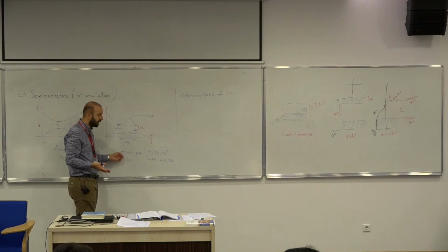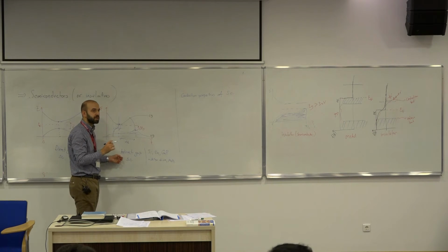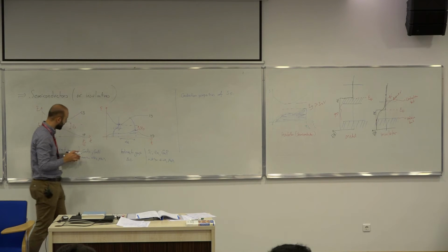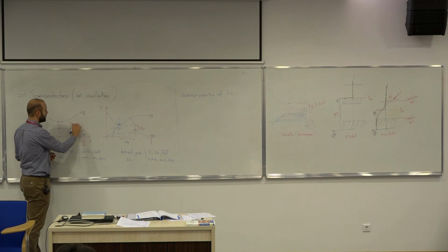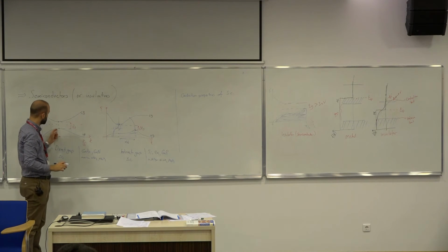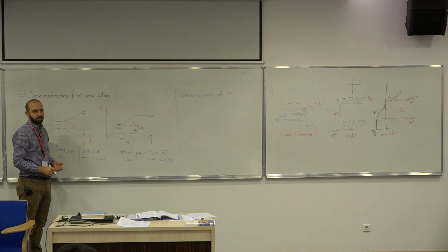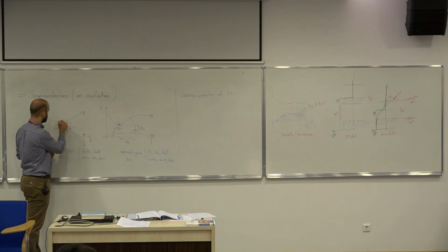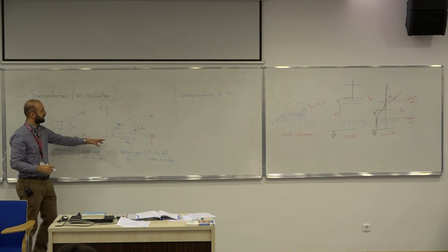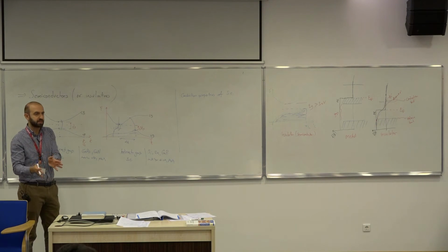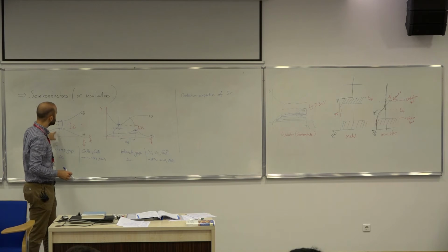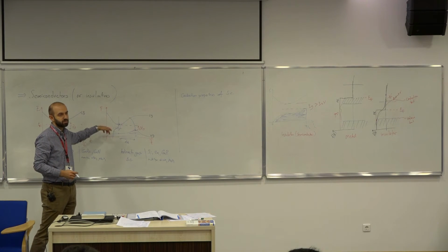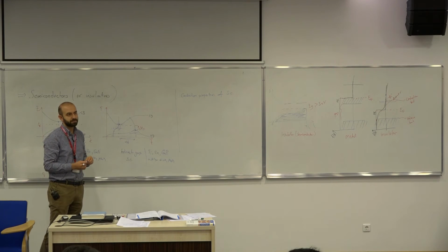So for indirect gap semiconductors, it's not a good idea to use them in optoelectronic applications. That's why these materials are much better in optoelectronics, because all you have to do is supply this energy, the energy required to take one electron from here to here, or vice versa. When you have an electron that's going to relax back, it doesn't need that momentum difference to be supplied from the lattice or scattering events or any other mechanism. This is much more probable compared to this one. So mostly it's related to the optoelectronics.